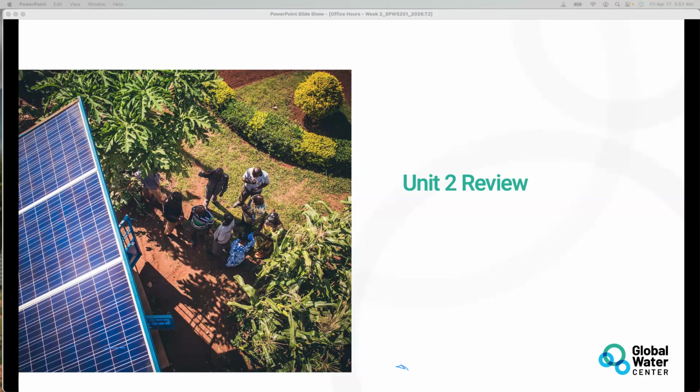These two amounts, maybe you will discuss them next time: the 4 meter cube per hour and 7 meter cube per hour target flow rates to start the pumping test are taken from other surrounding boreholes.